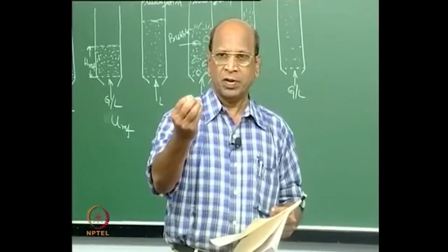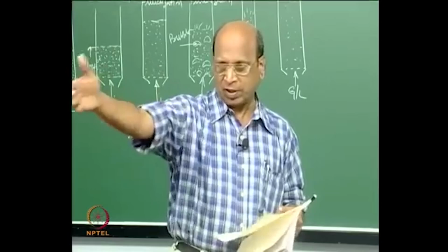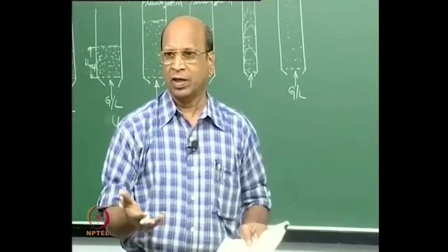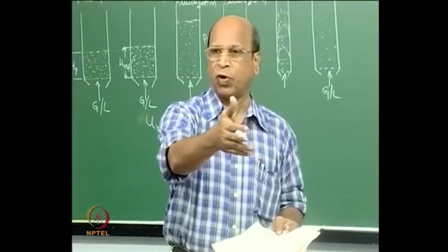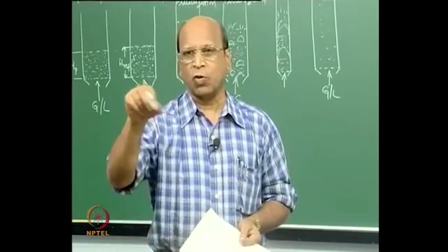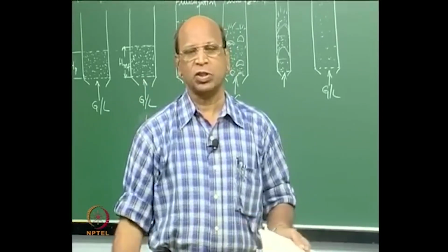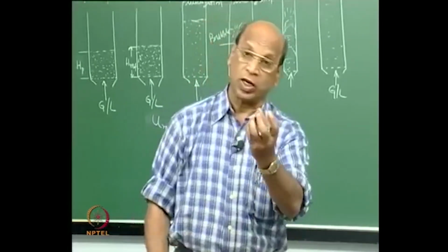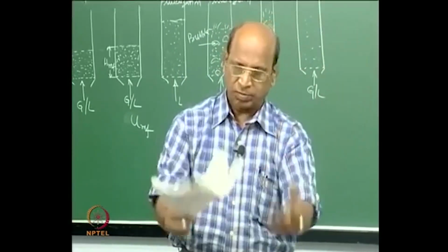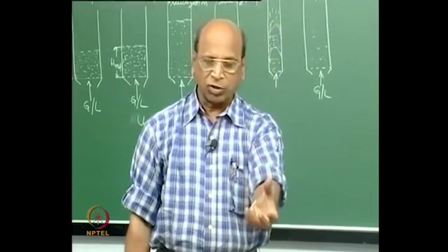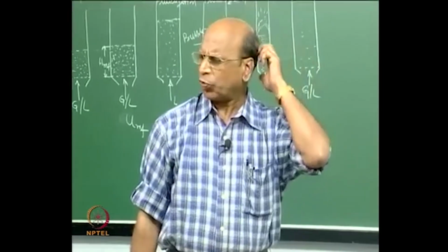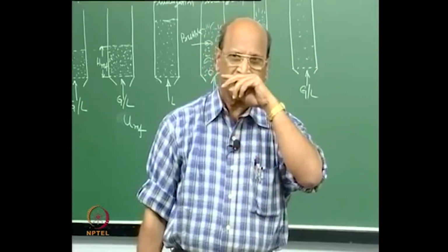Sulfur will react with oxygen, because for combustion, you have to send oxygen anyway. So, sulfur dioxide will form, CaO plus SO2 plus half O2 will give you CaSO4. CaSO4 is now solid, it is not going to the Taj Mahal now, it is only at the bottom you will collect and try to use CaSO4 for something. Okay. CaSO4 is nothing but gypsum, no? Yeah.